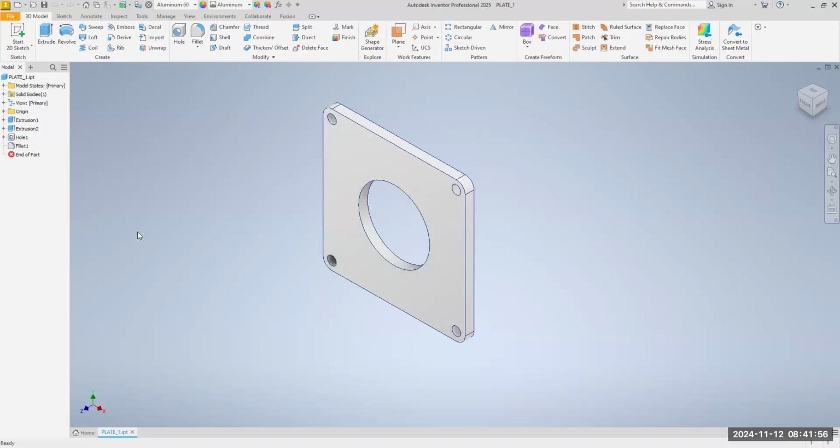And like I said earlier, please understand in the real world, we would have to create a larger hole here somewhat to allow the pipe to fit into the hole. Right now, you have to heat it up and force it in and then cool it down, and then you're going to have residual stress throughout your part. Thermal stresses. And that's an engineering topic we're not going to cover, but that would be a problem.